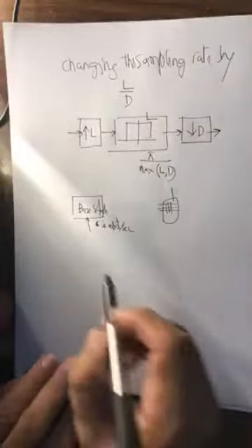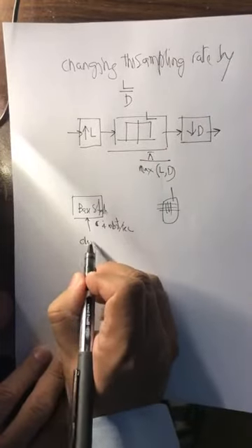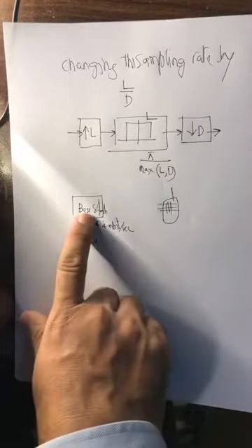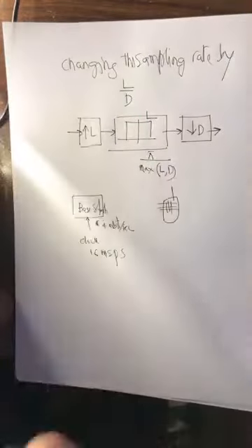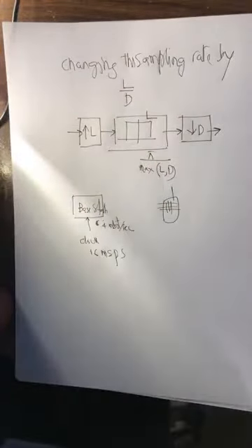So there is a clock which runs in a base station which has to work at this resolution, 4 megabit, and every bit in 4 samples, so 16 mega samples per second at the base station. So there is a clock which is measuring this time, one sample, another sample, another sample, another sample. Then there is a clock in your mobile phone as well, because it has to receive. They got to be synced.